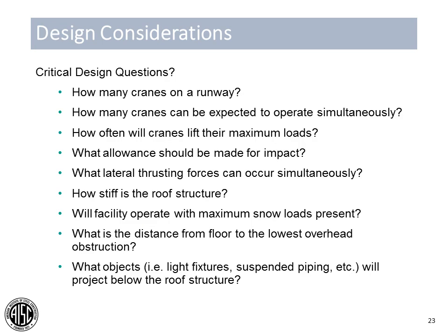As you begin your design, you need to consider a vast array of questions which are not typical for a general superstructure design that we would be used to. It's generally good to discuss with your owner how they're going to be utilizing these crane systems. How many cranes will they have within a particular runway or within a particular bay in a building? How many of these cranes can be expected to operate or are possible to operate simultaneously?